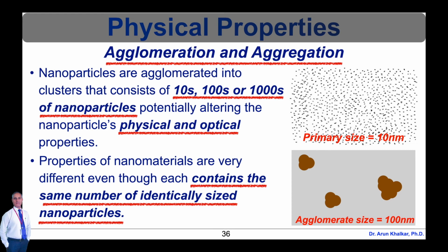However, even with the most powerful dispersion mechanisms such as probe sonication and milling, it is typically not possible to restore agglomerated particles back to a monodispersed suspension consisting only of individual nanoparticles. This is due, in part, to the relative strength of the van der Waals forces that bind particles together and the shear forces that can be applied on the nanoscale. In order to separate two agglomerated nanoparticles, forces in different directions have to be applied to each nanoparticle.